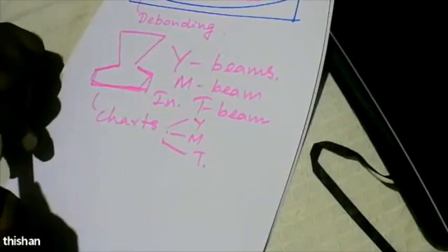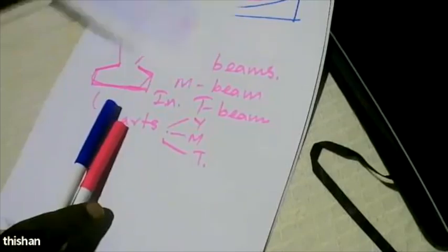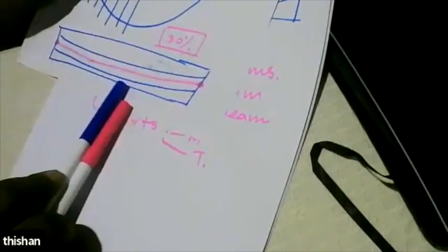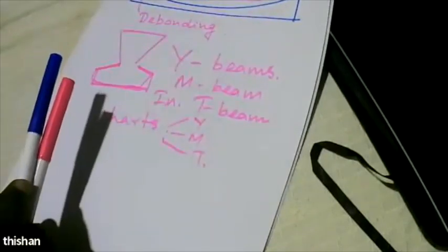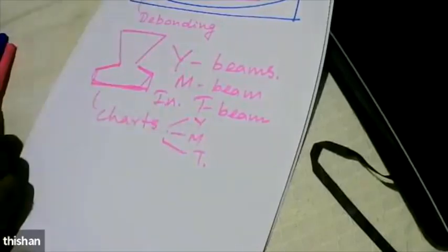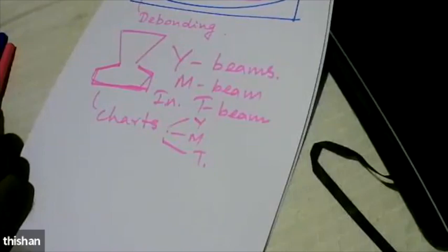The only thing is, once we come up to this level, either pre-tension or post-tension, then we have to do many other calculations, like you have to calculate the losses as shown. The R value of 70% is a valid assumption. Then you also have to check it for shear, and you can check it for deflections. So those are standard checks that you have to do.